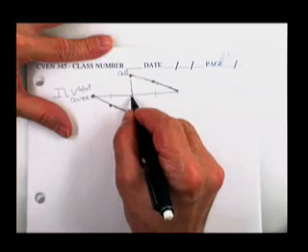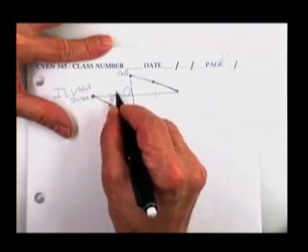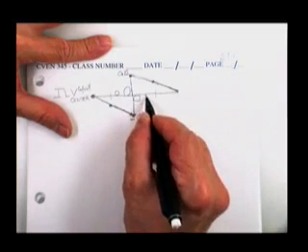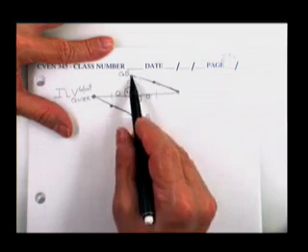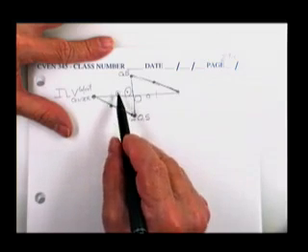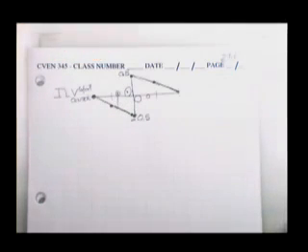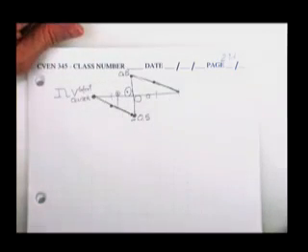You'll put the big wheel here, and you'll put the little wheel here, or you'll put the big wheel here and you'll put the little wheel there, and you'll multiply the magnitude of the big wheel times 0.5, and you'll multiply the little wheel's value times its influence. You'll add them together and you'll be able to design the beam for shear at the middle. And you'll do every point along the beam to make sure that the shear doesn't get too big.